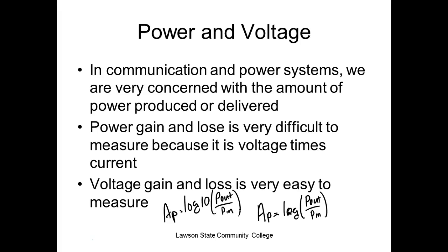Using that, finding a series resistor and calculating what voltage we expect to get a certain current, or we've been measuring it and using that to calculate it. What we're doing here is we're dealing with dB. Are we okay? So it would be real easy for me to measure voltage. I could take my scope and put it on the input, put it on the output, and I could very easily see my voltage. So I could take V out over V in.